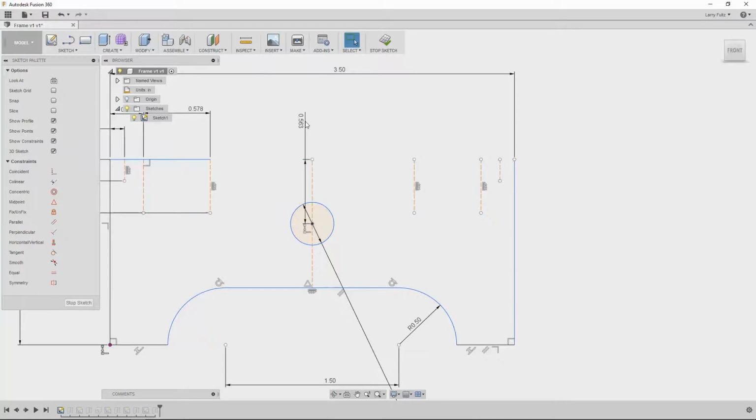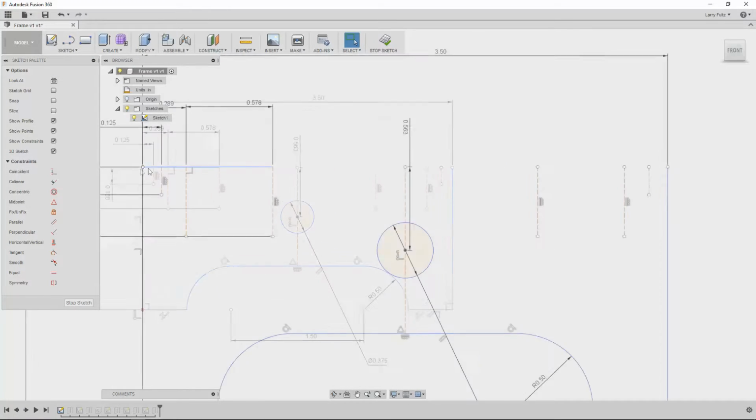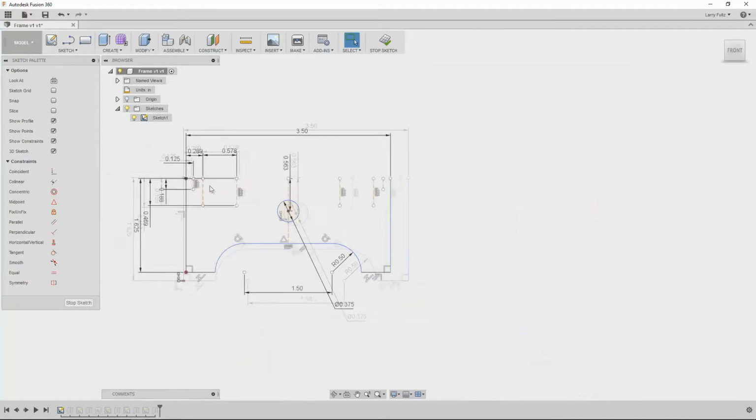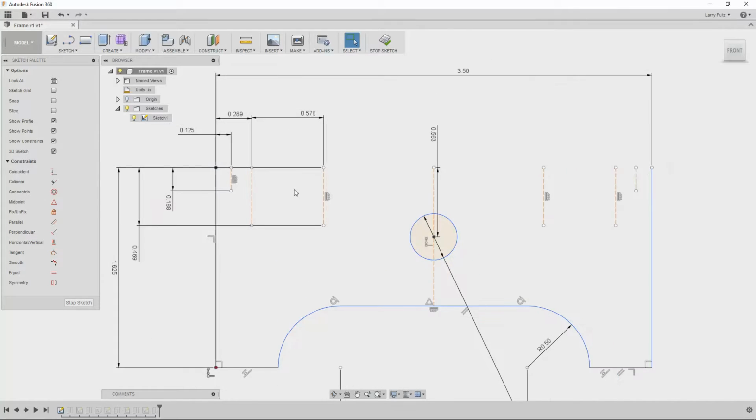This is just for the dimension here, so we're going to move that in so we understand that that's a dimension line and we're not trying to delete that later. Once again, get rid of all of our orphan lines. And again, that's a dimension line here. And we can actually get rid of that because we don't need that, that's 0.469. Let's make this a little bit closer to the end here. So hit D, dimension, do 0.469.